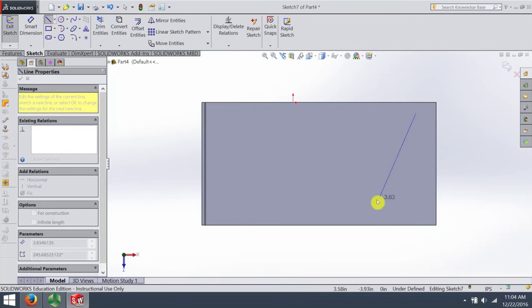Do make sure that these sketch bend lines that you're putting in are really vertical or horizontal. If you kind of eyeball it in there and you don't get it right, you'll get a bend, but you'll be wondering why that's an uneven flange later. It's taller on one side, shorter on the other. So just make sure that's horizontal or vertical, whatever you're working with.